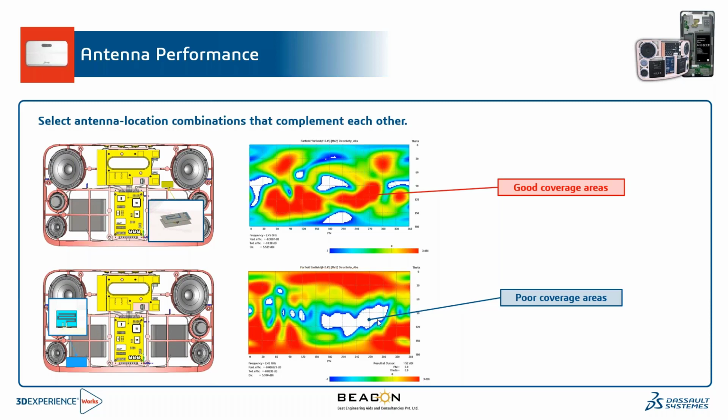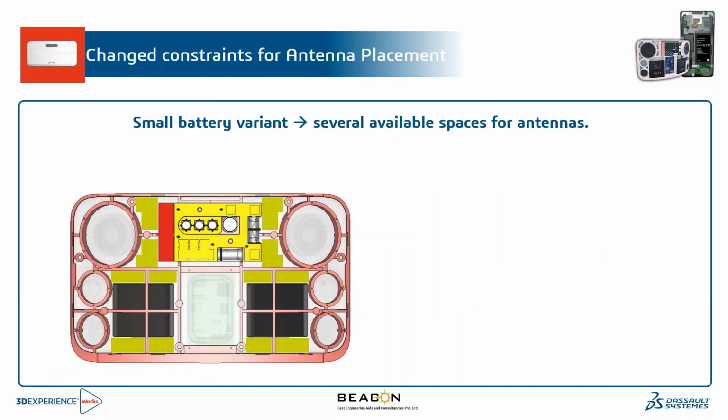And here, there is a very poor coverage area, which provides scope for improvement. We can see that at 0 dB, the total coverage efficiency upon choosing various types of antenna with various placement positions, we got the coverage efficiency to be 85.3, which is appropriate.